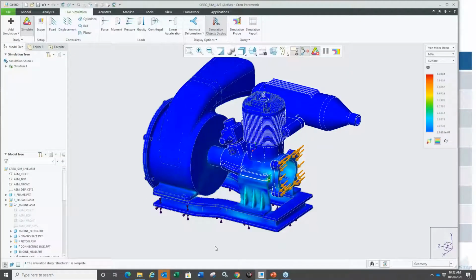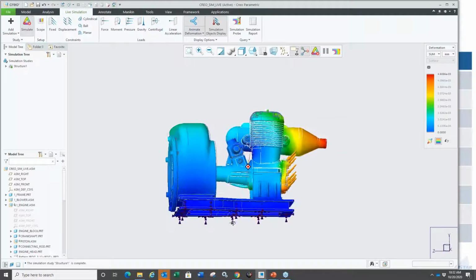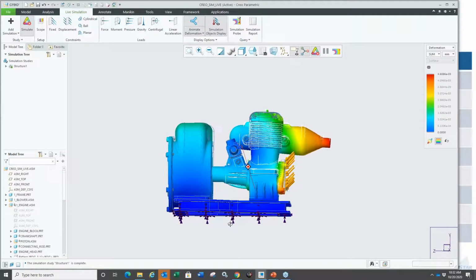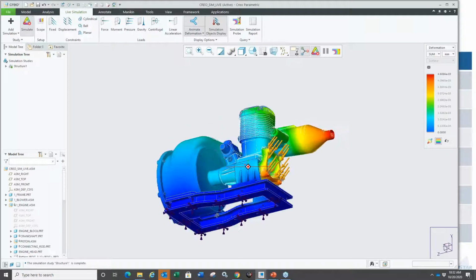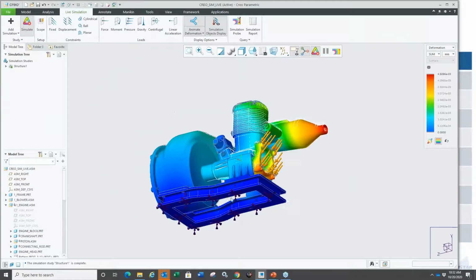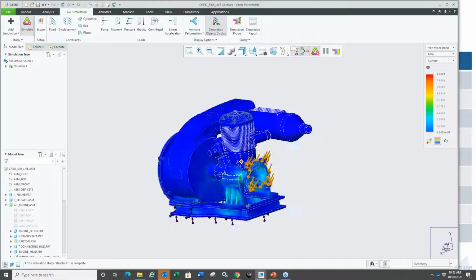And this is not the tool for that. If you want to do high-end nonlinear analysis, yes, there are other solutions, but this is mainly meant to give you an idea about the overall linear type analysis, simple ones here. You're not spending time meshing it. Everything is behind the scenes here, and it's just using your graphics card's GPU. There's your deformation, there's your stress plot.